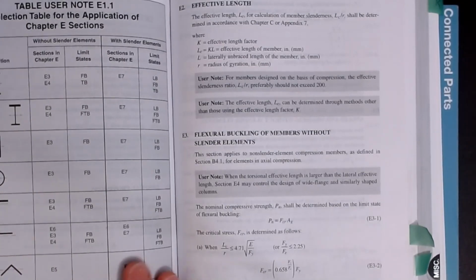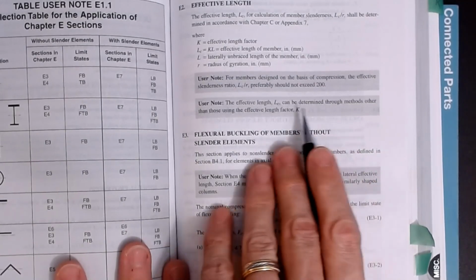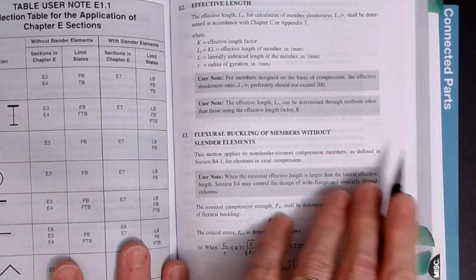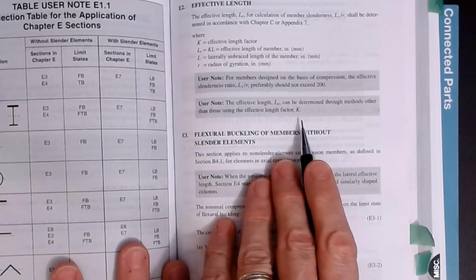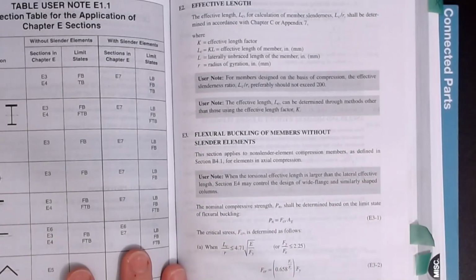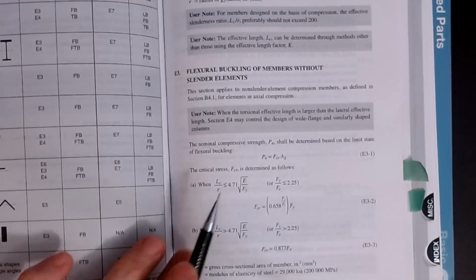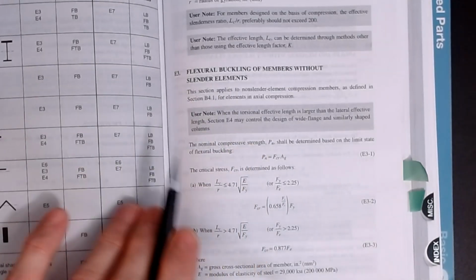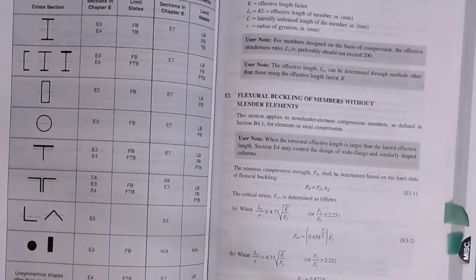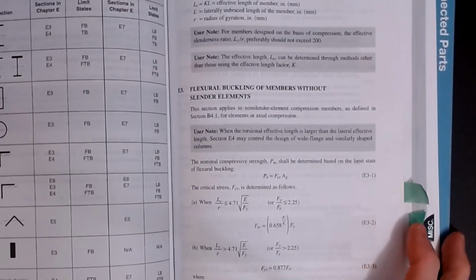Okay, they also say that you can use other methods to find K, whether it's through experimentation or whatever. You don't have to follow their K values, but you do need to be able to prove the K that you're using. So most of the time we just use the theoreticals or the recommended values that were back in that Appendix 7. Okay, so the basic expressions for the buckling of members without slender elements are given by this. And so what we're looking at is the rules that they're writing for compression are not just for columns, they're also for plates and for stiffeners and any part of a member that is subjected to compression and the behaviors that we can expect to have happen on those.